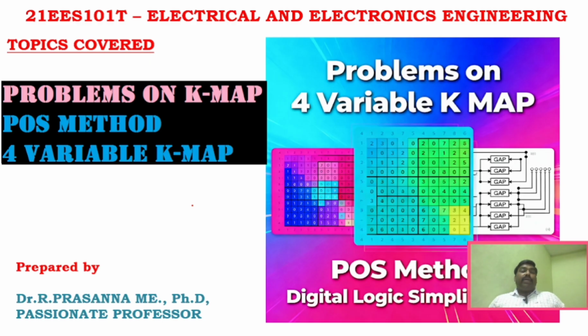And today's video is about another interesting concept in electrical and electronics engineering. We're going to see problems on K-map. We're going to see a 4 variable K-map problem for POS method, right?